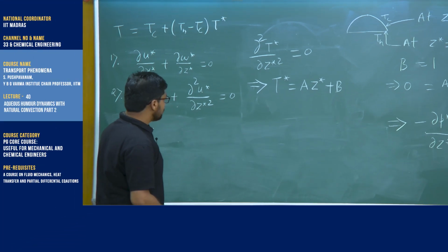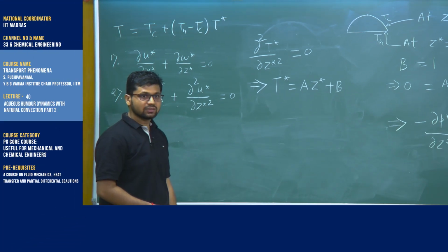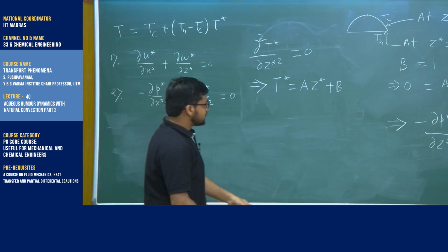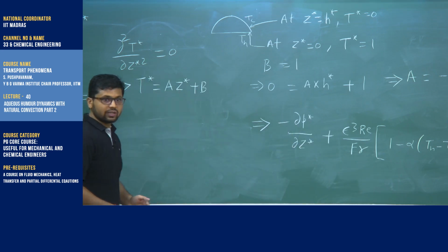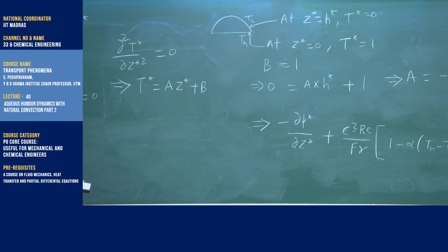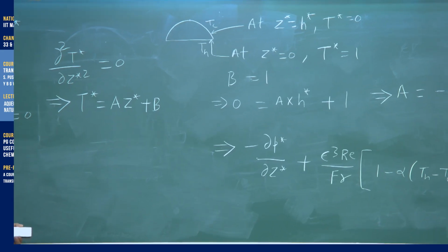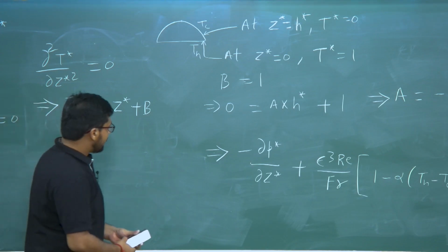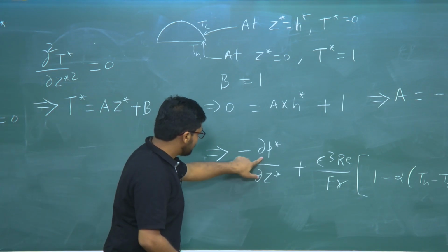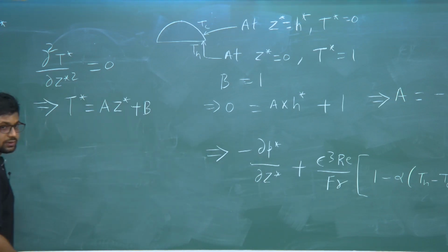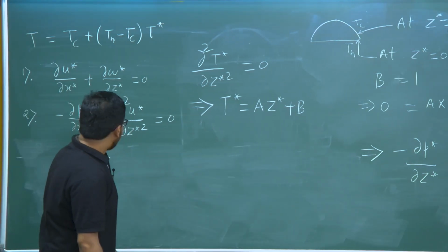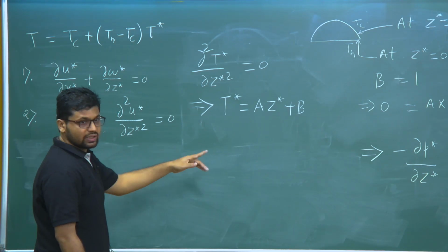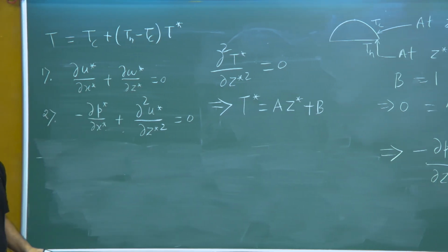As you learnt when sir was teaching the stream function formulation, we know that pressure is a dependent variable, right. So, we always want to eliminate pressure from our equations in most cases, and that is why the stream function formulation was created, so that pressure will not come in the equation. In a similar way, we will try to eliminate pressure from both these equations. We have this as x momentum and that as z momentum, and we want to eliminate pressure using these two equations. So, how can we do this?